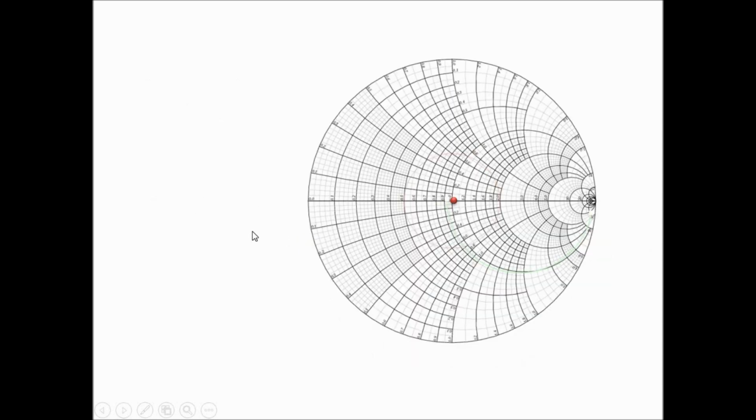So how can we find 0.16? We need more points because 0.16 and 0.34 cannot be obtained accurately by using the Smith chart we showed before. But this one has more precise points here, so we can get these numbers accurately. At first, this is the center of the Smith chart. So this has 1.0 here.